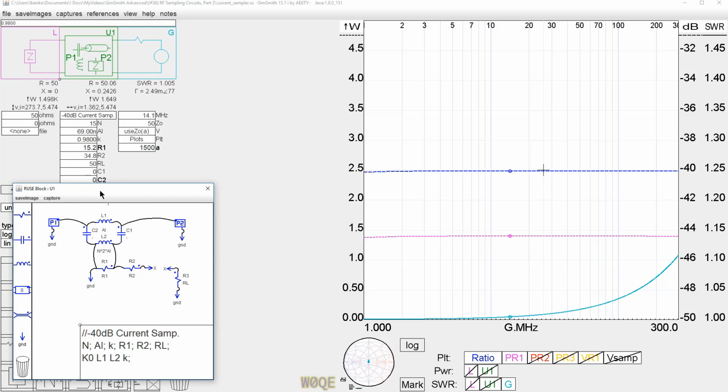In the circuits I've built, this overall number is less than a picofarad for the total when I've measured it. So let's say this is maybe 0.3 picofarads, and this is 0.3 picofarads also. Now what we see is the coupling factor starting to change. It doesn't change a lot, but it's starting to change a little bit here. And let's look at that a little more closely.